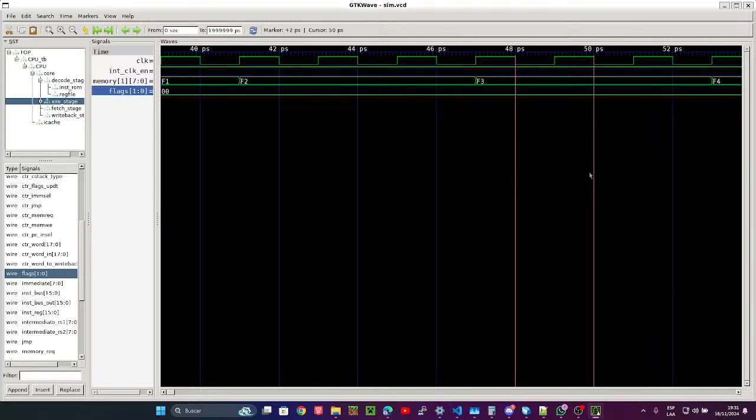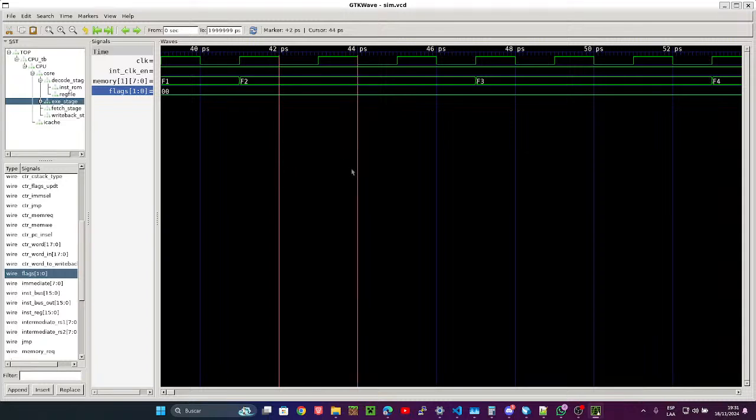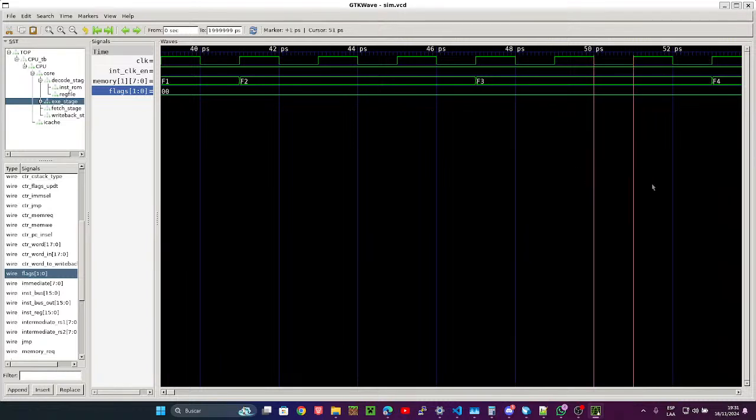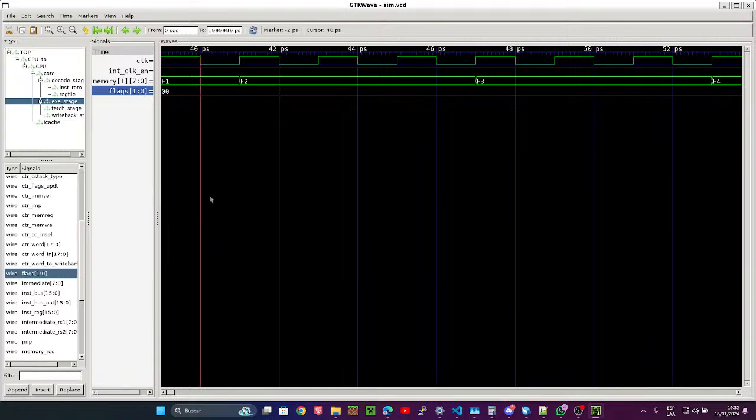Another thing they don't usually do is they don't have that deep of a call graph. They only go like 4 or 5 layers into a function calling another function, and that's why everyone does hardware call stacks. Nobody who is going for maximum performance is doing a stack pointer and stack in memory. For example, the BatPU2's call stack is 16 deep. I could actually change the size to something larger because that doesn't affect software at all.